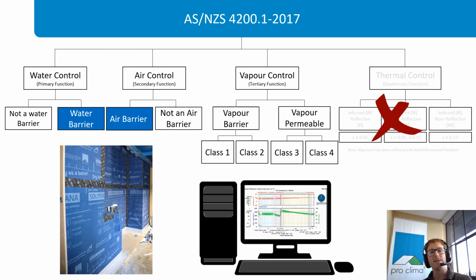So the only way to really make all this work is to test the system under a full-scale NZS 4284 test for weatherproofing, make sure that all the details are weatherproof, and then define the properties of the external materials based on simulation. Because we can't build a system and wait to see if it goes moldy, we have to use validated empirical tools to work out whether the system is likely to work from a drying capacity perspective and not end up with high humidity in the system.